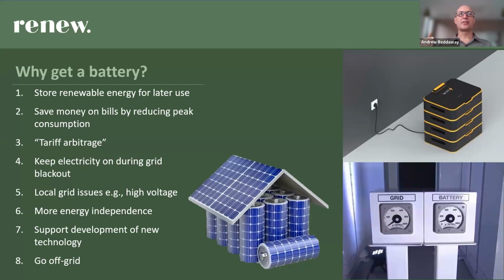Another level of that is, okay, even if your battery can power your house during a grid blackout, can your battery charge from solar during a grid blackout if you've got a blackout during the middle of the day? So that's another thing to check as well. There are systems that can do that.